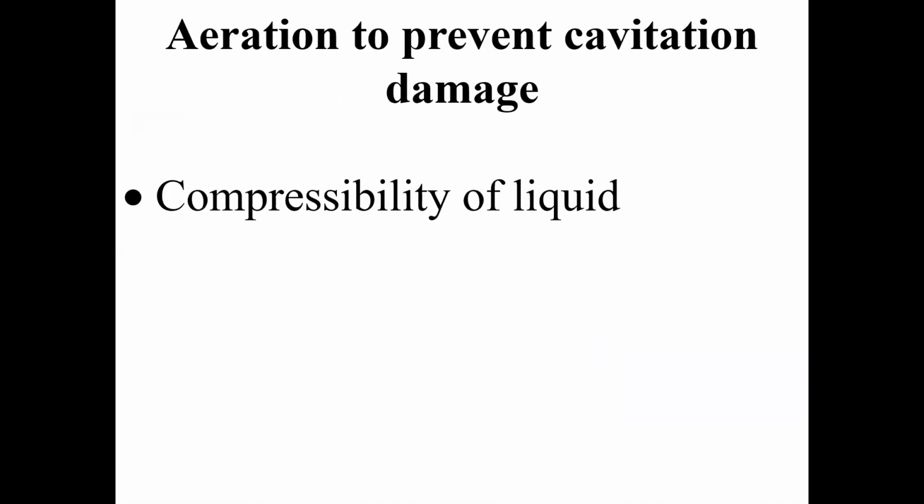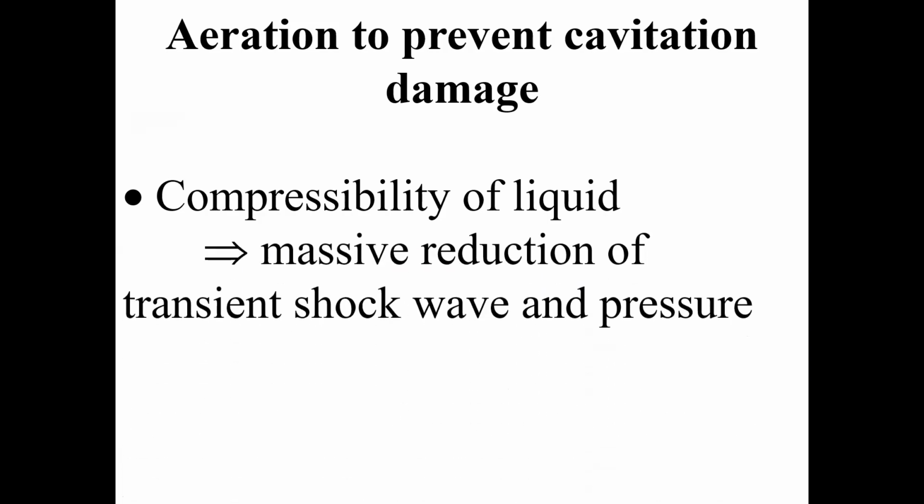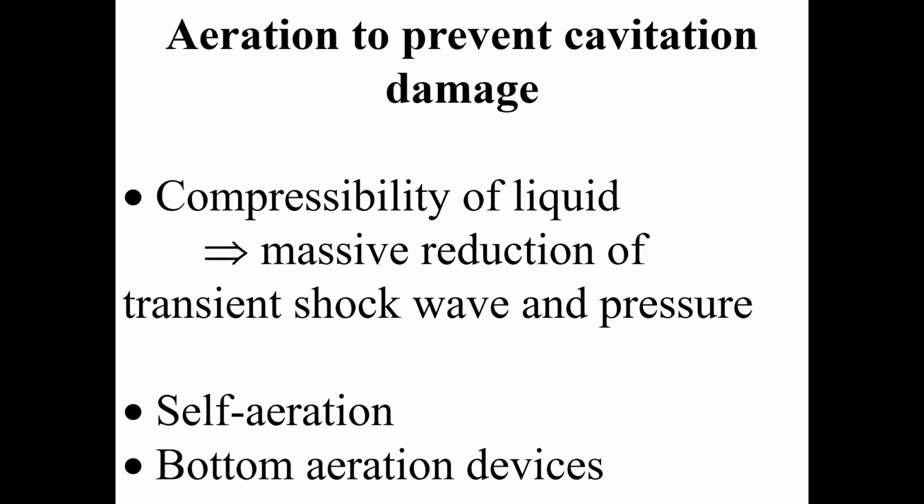The aeration of the flow will increase the compressibility of the liquid by the presence of the air bubbles, and in turn lead to a massive reduction in the transient shock wave and pressure. Aeration could be in the form of self-aeration, but most often we will artificially introduce air through a bottom aeration device or bottom aeration slot.